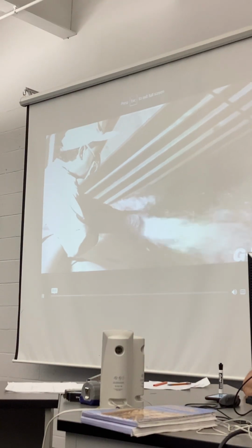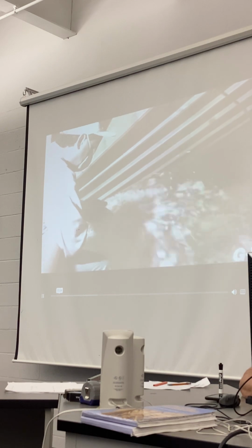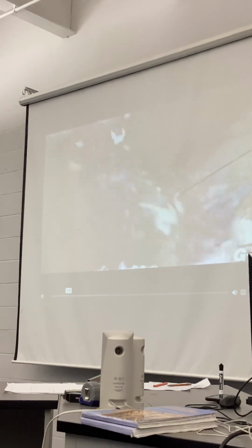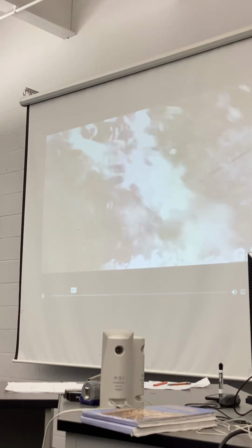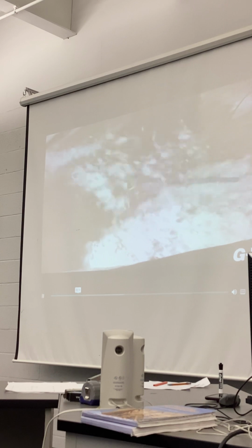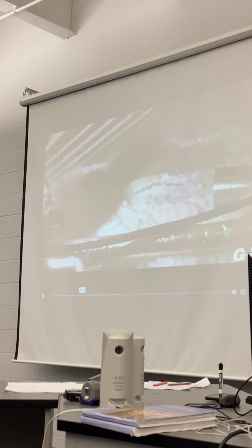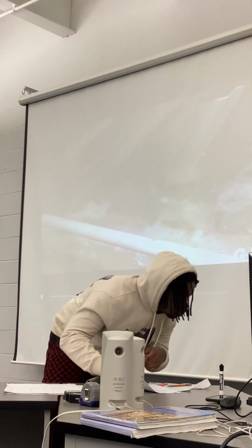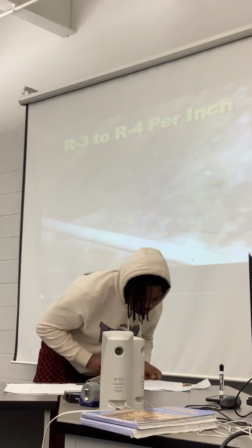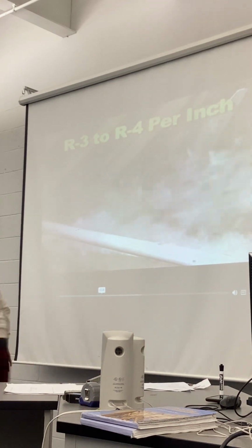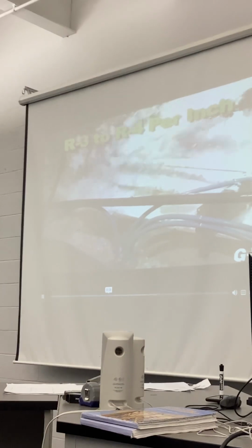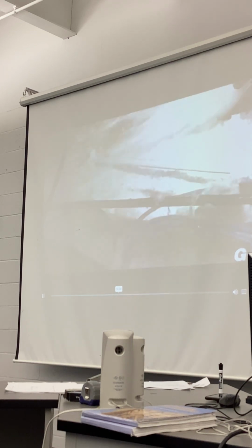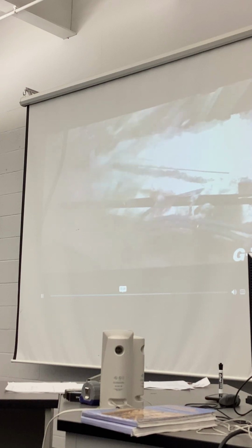Loose fill insulation, usually made of fiberglass, rock wool, or cellulose, comes in shreds, granules, or nodules. The loose fill material conforms readily to building cavities and attics. Therefore, loose fill insulation is well suited for places where it is difficult to install other types of insulation. Loose fill insulation typically has a value of approximately R3 to R4 per inch. Cellulose fiber has approximately 30% more insulating value than loose fill rock wool.